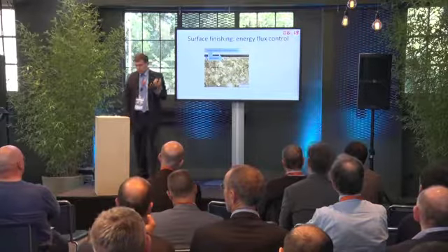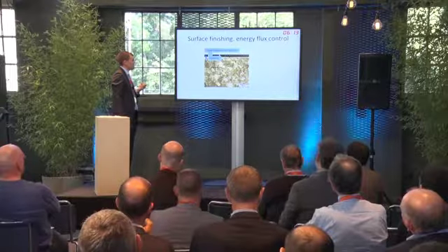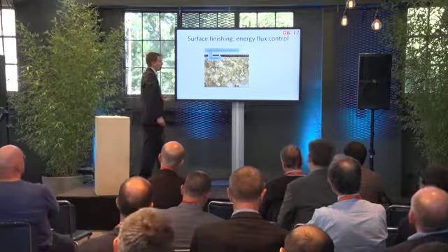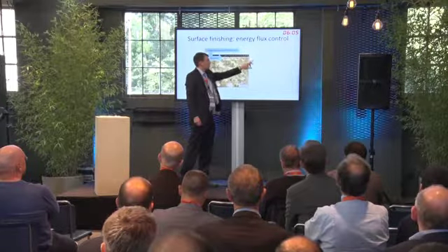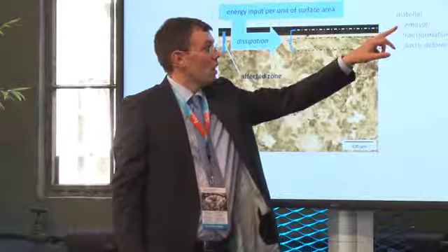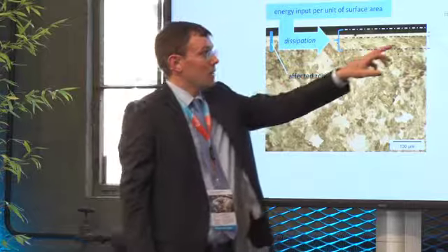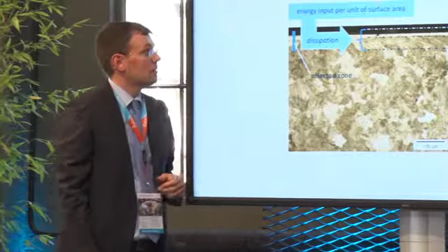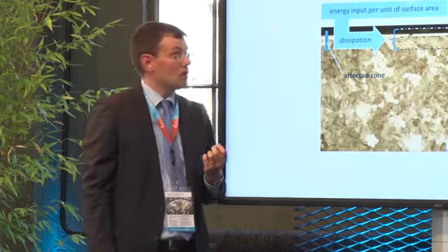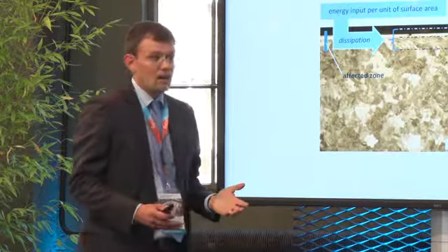And I think that you can capture with such a model any surface treatment method. It can be grinding, milling, or whatever. And I think in order to have a proper process, you have to tune the distribution of the energy over these 3 processes. And I will go deeper in that. If you exclusively tune this one, removal, you can get a very bad surface, and you can reduce the lifetime of your surface with large factors, and I will also come back to that as well.